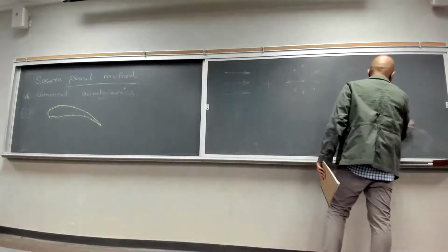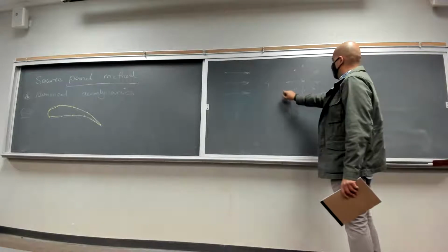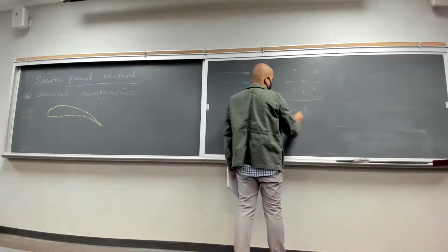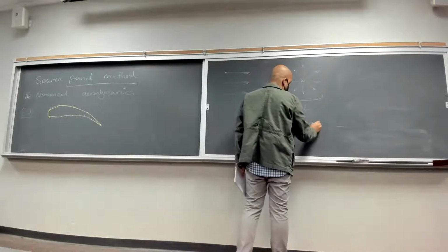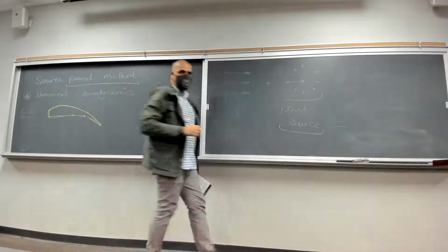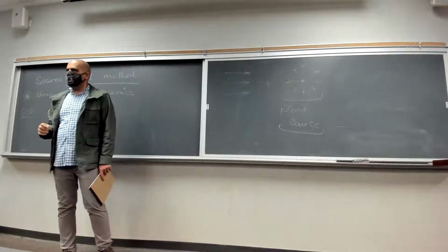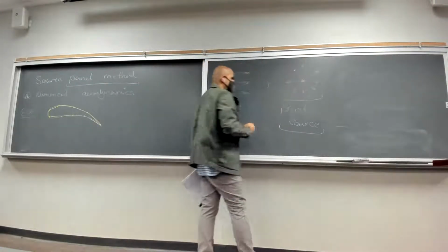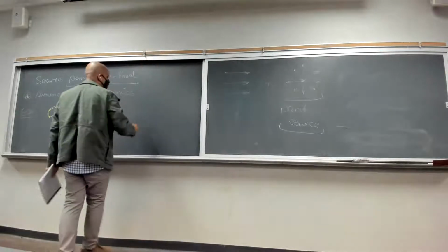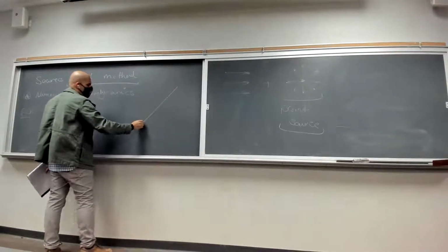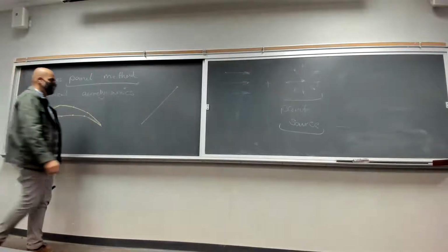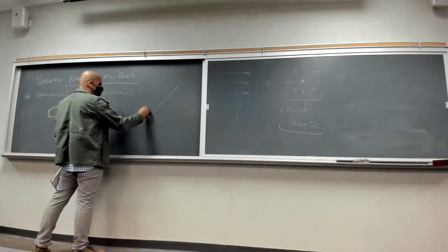This elementary flow that we have talked about so far is a point source. We want to extend this to become a line source. So instead of having one point as the source of the flow, we are going to have a line as the source of the flow, which essentially works like this.